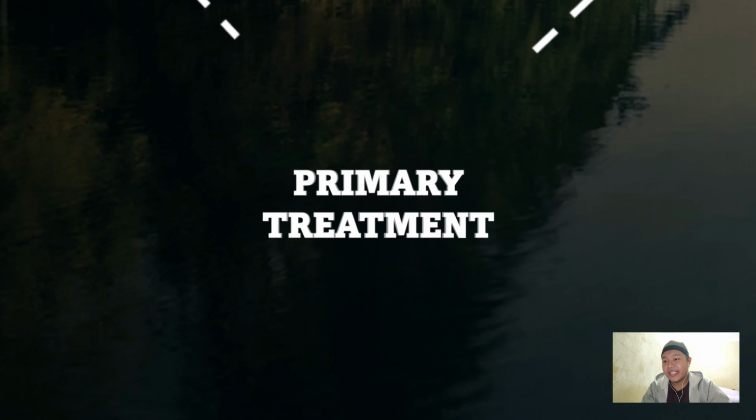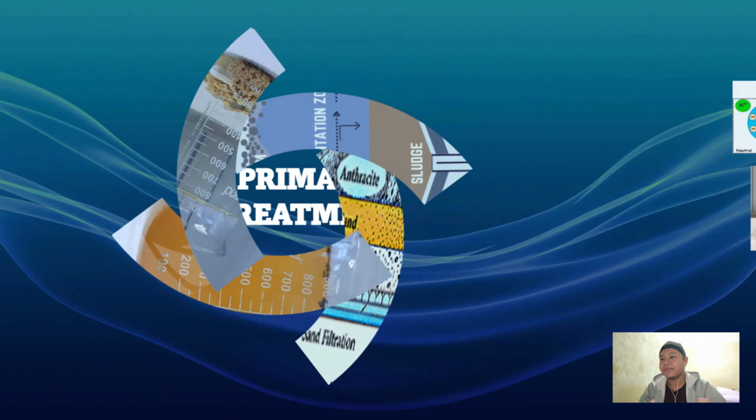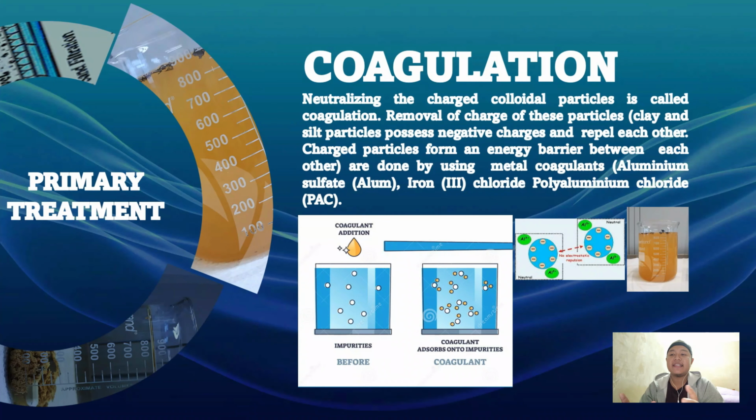So moving on to the next process, which is the primary treatment. In primary treatment, there are 4 important steps. First, coagulation. In coagulation, the aim is to neutralize the charged colloidal particles. In other words, to remove the charge of particles, which are usually negatively charged and repel each other.